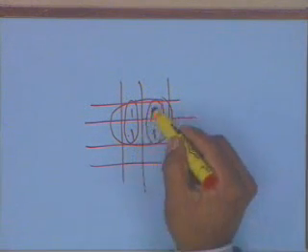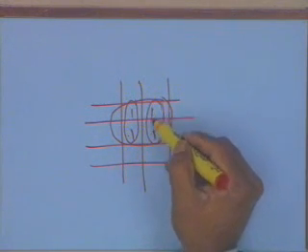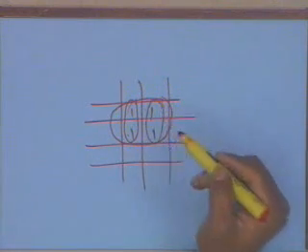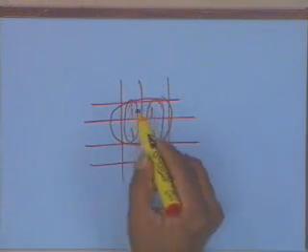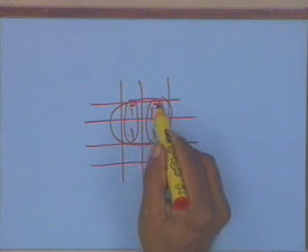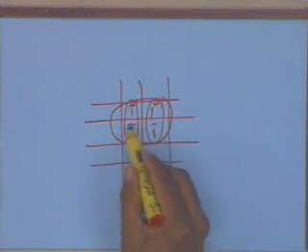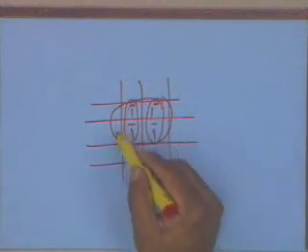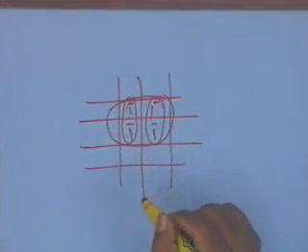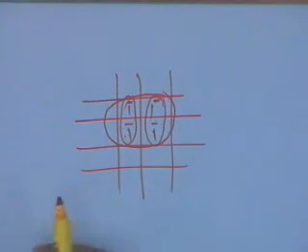To be able to do that, I should have eliminated the same variable in both of these product terms. Now if you look at the minterm value here and the minterm value here, they will differ by some 2 raised to the power i, and these two will also differ by the same 2 raised to the power i. Then in this case I will be able to combine all these 4 of them together.